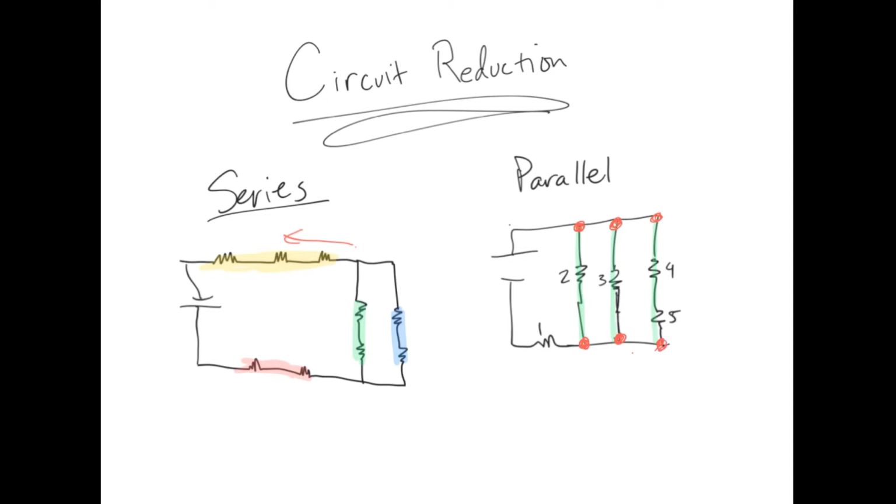Or here to here. You can really think of all of those wires as just combined into one big, let me just redraw this. This would be like a circuit that just has one big joint here that splits into these three channels, and they all come back together into another spot here. And so this point to this point, if you tapped across that with a voltmeter, you'd get the same potential difference. And so it doesn't really matter which branch you're talking about, whether this branch, or this branch, or this branch, you'd get the same voltage drop or potential difference. So my ski hill analogy: for parallel, it'd be like if you were up at the top of a run, no matter which run you went down, 1, 2, or 3, you would drop the same amount of height by the time you got down there.